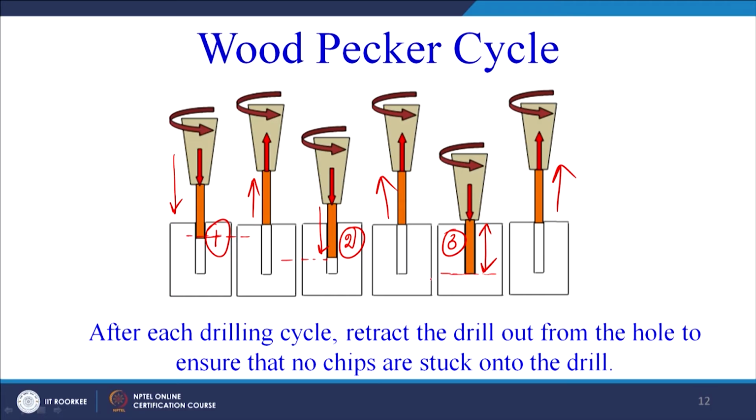After each drilling cycle, retract the drill out from the hole to ensure that no chips are stuck onto the drill. So this is one approach which has been found to be applicable, especially in case of very thick composite parts or very thick composite laminates made by polymer matrix and reinforcing fibers.